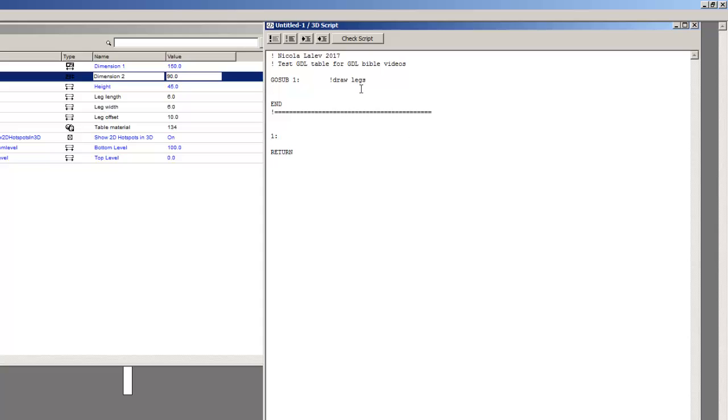The second command will be draw table plot, and that's the command. Since the material is tmat, we'll use that by typing material tmat. Therefore, every command which creates an object after that material tmat will use the surface defined in the tmat variable. Now let's create the second subroutine. And check. Of course, it's correct. We've created nothing for now.